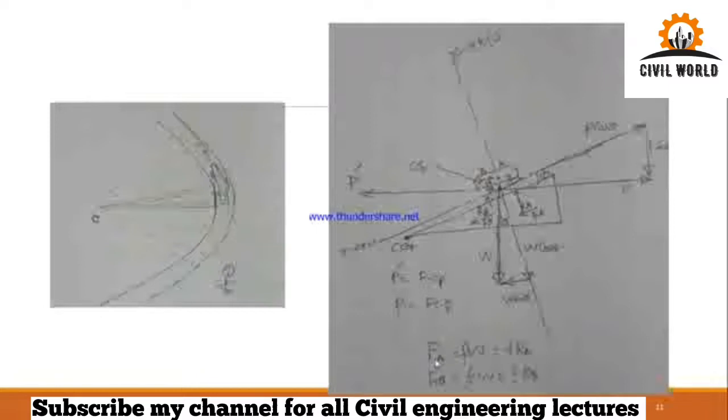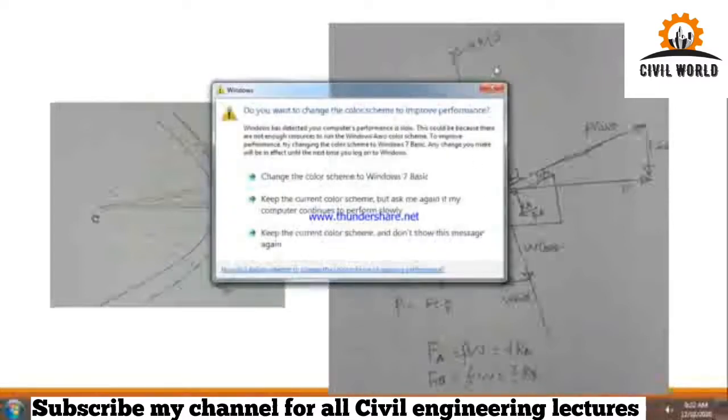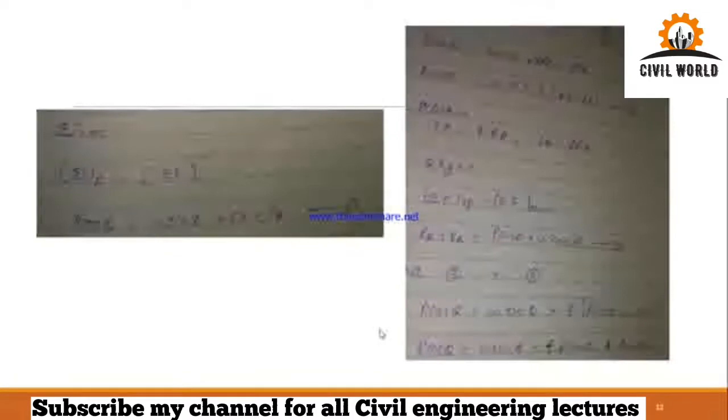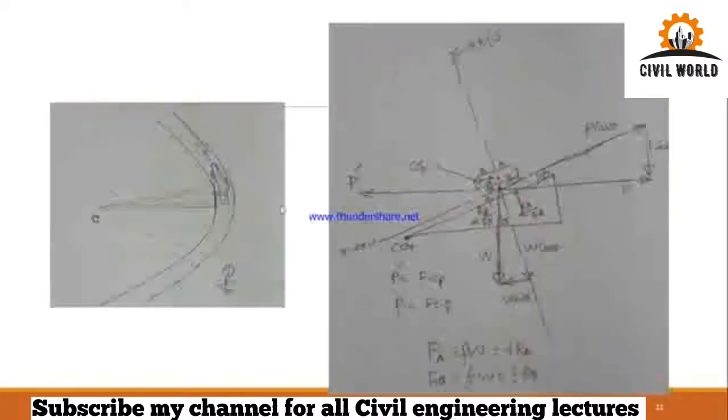Here FA is a frictional force which depends upon the friction factor and the weight of the body or reaction of the surface, and FB is also a frictional force which depends upon the friction factor and the reaction of the surface. So FA is equal to F into RA, FB is equal to F into RB. Now if we apply the first condition of equilibrium, the summation of forces toward right is equal to the summation of forces toward left. So P cos theta is equal to FA plus FB plus W sin theta.